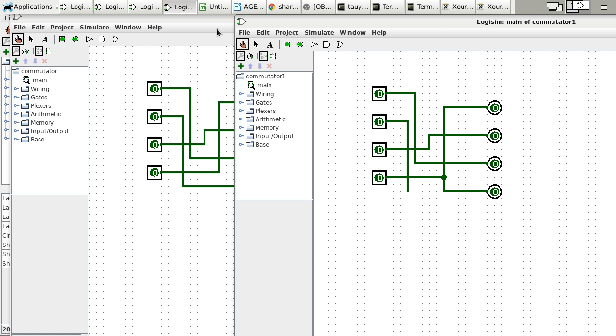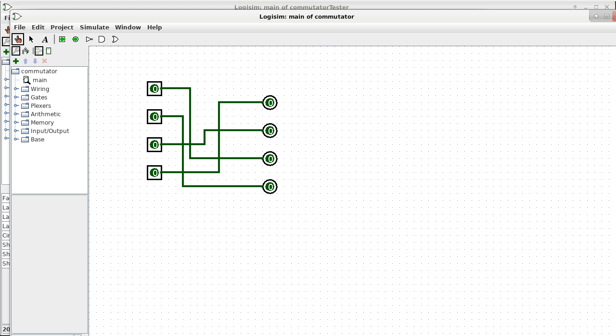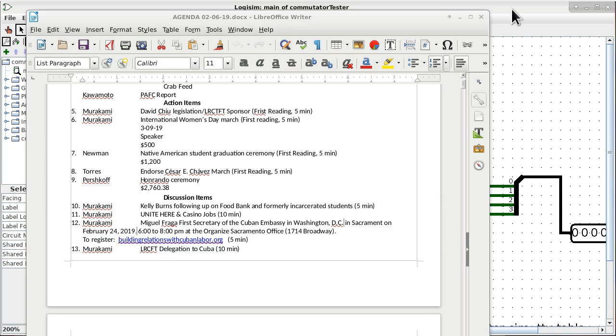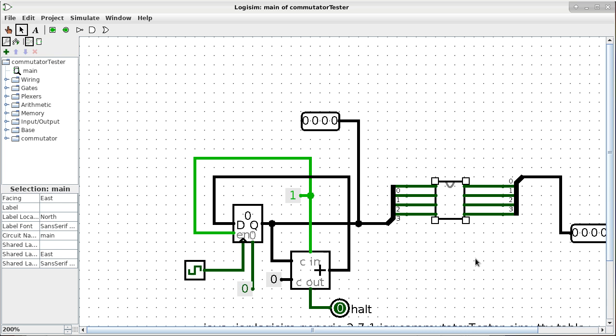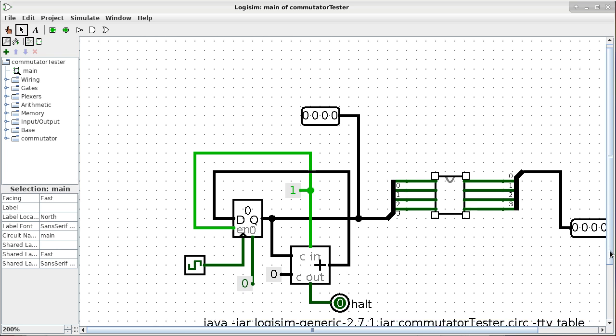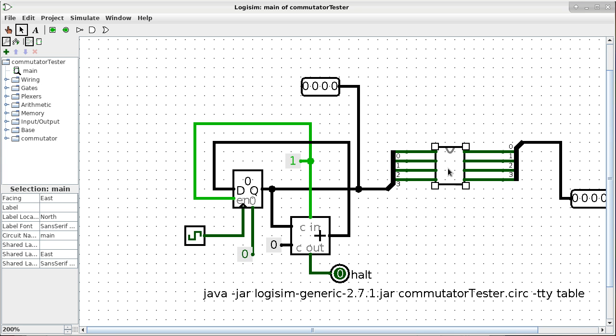Okay, so for those of you who really want to get into this and go like, I'm going to spend some extra time to understand the test circuit so I can build a test circuit for my own designs. This is the bottom line, okay? So obviously, the inputs and outputs would not be the same, but what you need to do is to change the width of stuff, okay? This has a width of 4, you need to increase it to 7, okay?